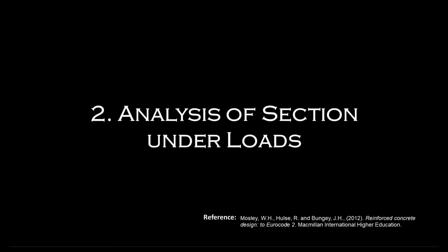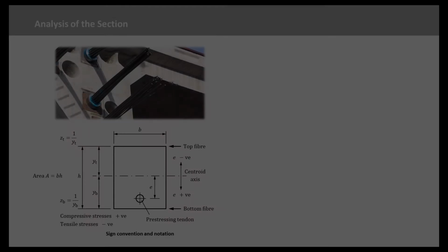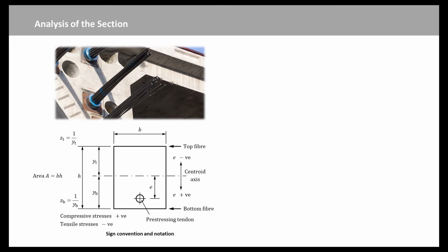Since the object of prestressing is to maintain favorable stress conditions in a concrete member under load, the working load for the member must be considered in terms of both maximum and minimum values. Thus, at any section, the stresses produced by the prestressed force must be considered in conjunction with the stresses caused by maximum and minimum values of applied moment. Unlike reinforced concrete, the primary analysis of prestressed concrete is based on service conditions, and on the assumption that stresses in the concrete are limited to values which will correspond to elastic behavior.